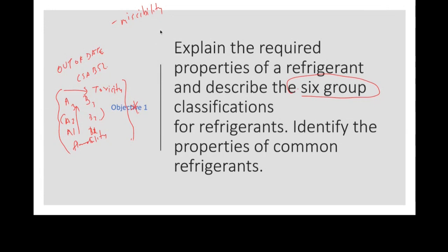So then we have to think, does the refrigerant sort of float on top of the oil, or does it sink below the oil, or does it mix in with the oil? We find certain refrigerants are miscible with certain types of lube oils, and others are not. And some are compatible with some types of lube oils, and some are not. So miscibility is an important feature of a refrigerant when we're considering a particular lube oil for the compressor.